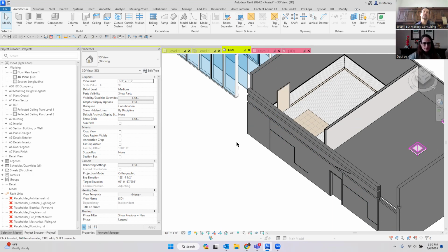Usually when I do a mullion on a situation like that, my mullion isn't a reveal. My mullion is gasketing because technically in tilt up or even precast, we're going to put some backer rod and sealant in there. So I usually will create a mullion that even looks like backer rod and sealant to a point. I mean, it's got to be a profile that goes through. So I even put the little grooves in there to look like it. But yeah, that's what I'll do for my mullions and make that 1/2 inch wide. So I'm not trying to put 2 curtain grids next to each other.